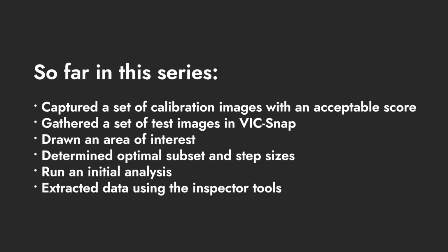It assumes that you have captured a set of calibration images with an acceptable score, gathered a set of test images in VIC-Snap, drawn an area of interest, determined optimal subset and step sizes, run an analysis, and extracted some data using the inspector tools.